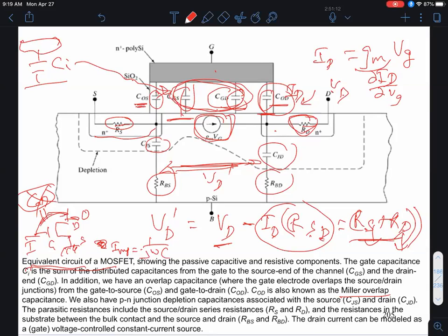However, you do need some overlap because if you ended up with a gate electrode, which was like this, say, okay? It didn't go all the way across the channel between the source and the drain. What happens then is, in these non-overlap regions, the gate cannot really invert the channel very well, right? So if you draw the potential profile, you'll end up getting additional potential barriers that the gate cannot control very well. And what do you think the impact would be on the transistor performance?